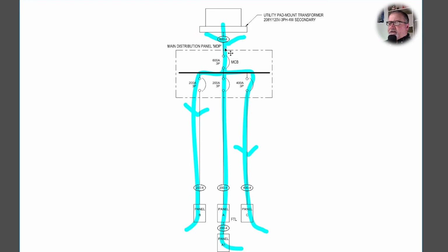So it's important to realize if we open this circuit breaker and actually have a gap in the wiring, everything downstream would be off. This is upstream, up the page in this case. Downstream is down the page in this case, but we just need to remember that upstream is towards the source, downstream is toward the loads. If we close this breaker again, then everything's powered up. If we open this 200 amp breaker, what turns off? Well, the power flow would stop at that breaker and everything downstream from it would not be on.